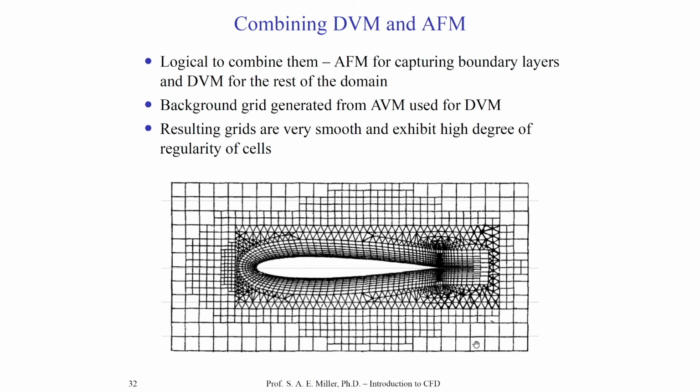First, the exterior domain is created and it is discretized with grid points. Then the airfoil is created on the interior, and we put a number of grid points around the airfoil. We would say we would like to have quadrilateral elements around the airfoil because they're better for regions of high shear. We find that in high-speed aerodynamics, typically elements which are not triangular or tetrahedral are better in regions of high shear because of the solver issues of well-posedness, because of the numerical issues inherent in the solver, which we'll talk about later.